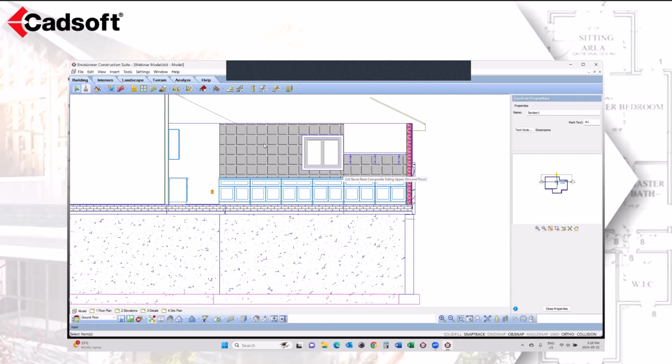So in this section view, where there was tile, I have put a simple tile hatch pattern on that wall. And inside the wall, where I had my core, I put a hatch pattern in there to illustrate batt insulation. And with both of them, you can see that I've added a color behind it as well.